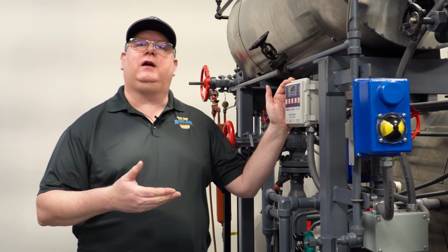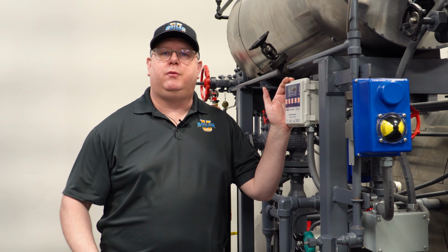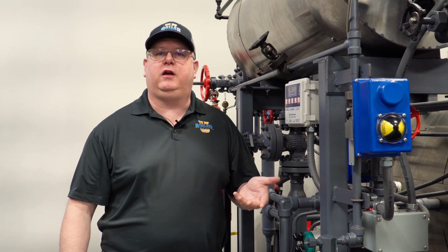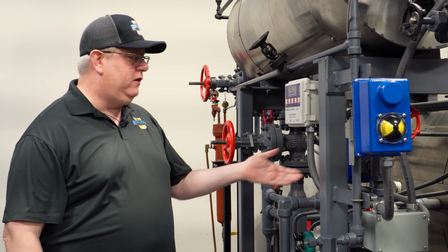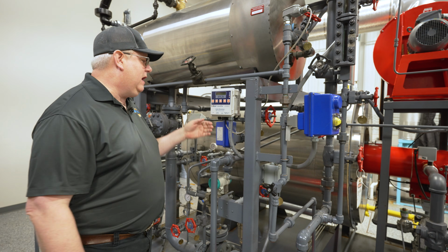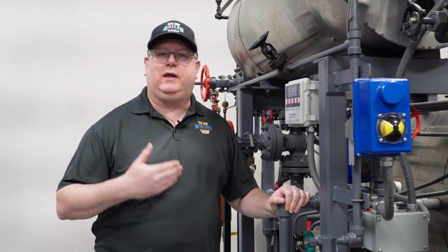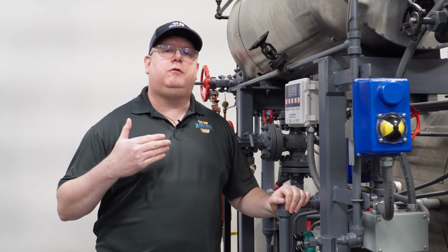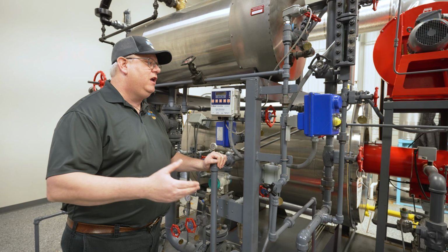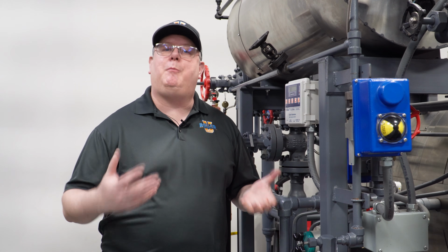But first, I just want to take a look at some of the components you may see on a boiler pertaining to conductivity control. One is bottom blowdown. So this is a flash steam generator, and it's got a bottom blowdown on it. Bottom blowdown is one way that we can control conductivity, but to be the most effective and efficient, an automated system is optimal. It's not mandatory.